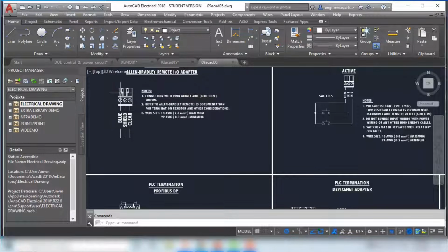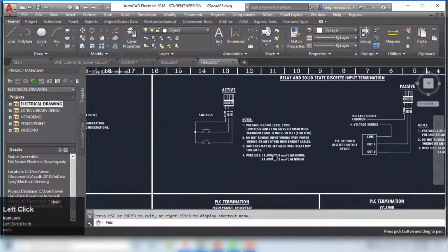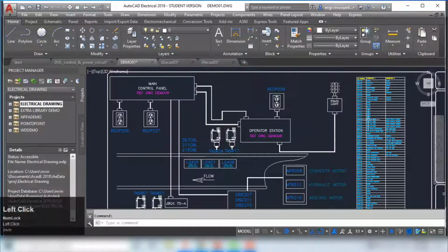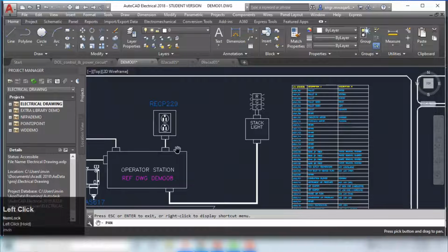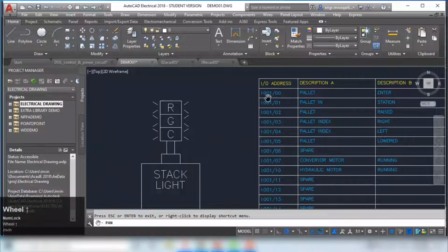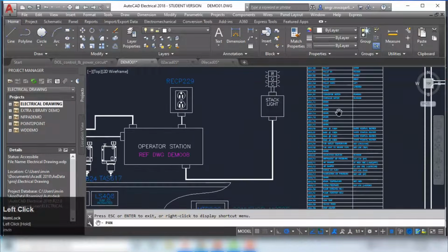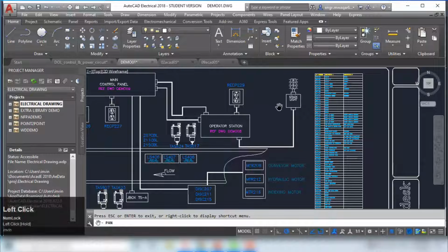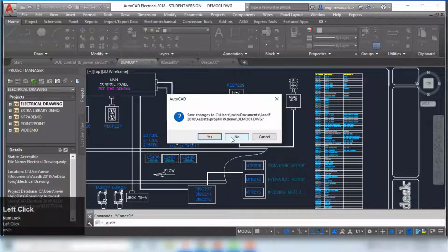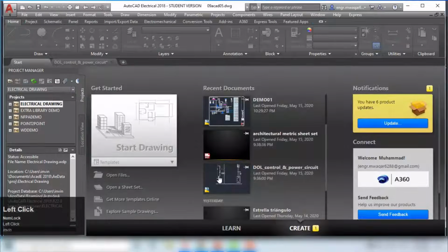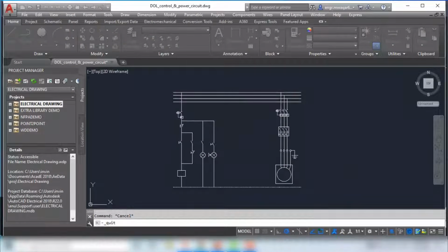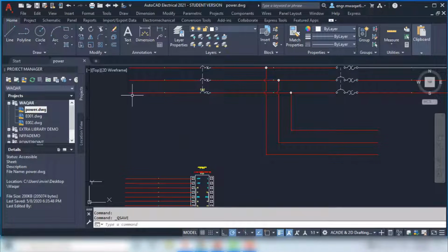That integration has to be the key, because the power here isn't just graphical, it's totally data-driven. The sources we looked at, they all highlight the report feature as being absolutely essential. Oh, for sure. It's not just a summary, is it? No, not at all. It's the strategic bridge between what you see on the screen, the schematic, and the entire logistics chain. The report feature gives you this complete, organized breakdown of everything in that drawing. Not just component names, but the critical details like I/O addresses, terminal info, detailed component descriptions. Wow. Mastering this one feature first saves hours of cross-referencing against a bill of materials later. That's where the real-world time savings happen.